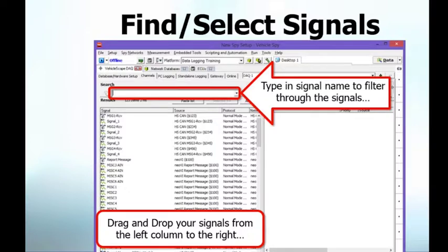And then also you can set up different conditions. So when we move into the next screen, we'll have different collections that you can set up. What's nice about that is, let's say you've got 3, 4 different collections that you're running, all with different triggers, and you want one trigger to get you CCP information, another trigger to get you just normal CAN. Essentially, you just right-click on those messages, and there's a condition set up, which I'll show you, and you say, I only want this data when this trigger's true. So that way you're not just always consistently recording CCP data when you don't necessarily want to be.